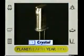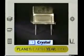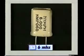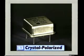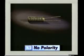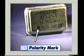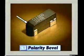Crystals, which are also sometimes called oscillators, produce consistent electrical pulses or vibrations. A crystal's value is measured in megahertz and is printed on the component. Some crystals have polarity, some do not. If they do have polarity, the direction of installation is indicated by an angled or sharp edge or a dot. On surface mount crystals, installation is marked by a beveled corner.